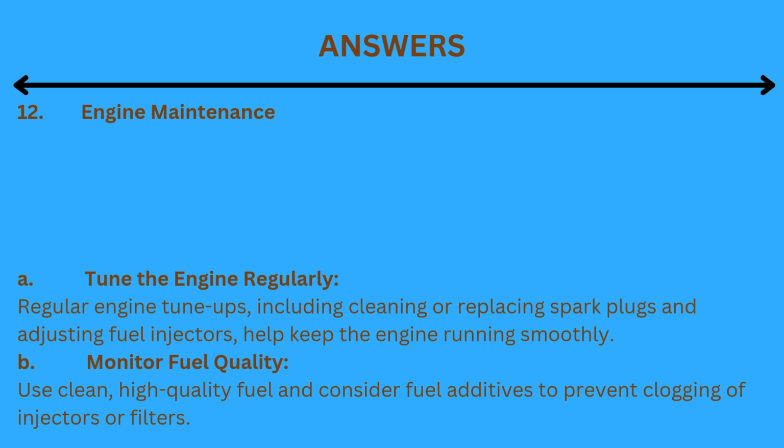12. Engine maintenance. A. Tune the engine regularly. Regular engine tune-ups, including cleaning or replacing spark plugs and adjusting fuel injectors, help keep the engine running smoothly. B. Monitor fuel quality. Use clean, high-quality fuel and consider fuel additives to prevent clogging of injectors or filters.